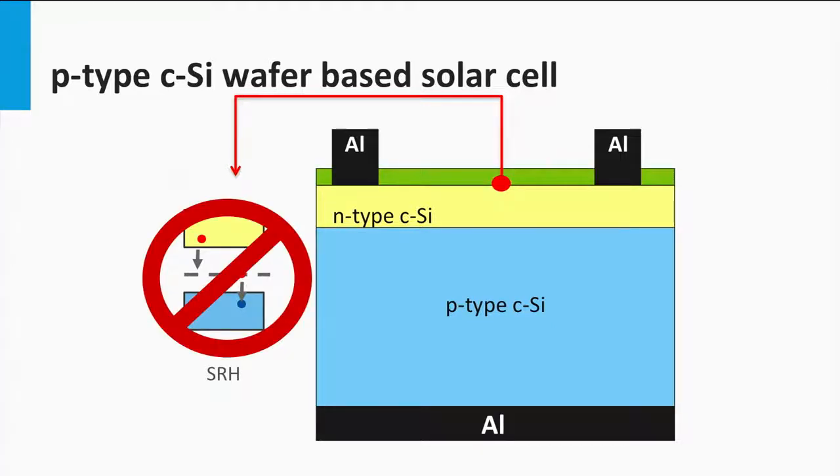The first is based on reducing the number of defects at the surface. This can be achieved by the deposition of a thin layer of different materials on top of the surface. This material partially restores the bonding environment of the silicon atoms. In addition, the material must be an insulator. It must force the electrons to remain in and move through the emitter layer.